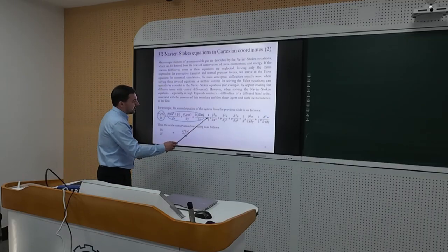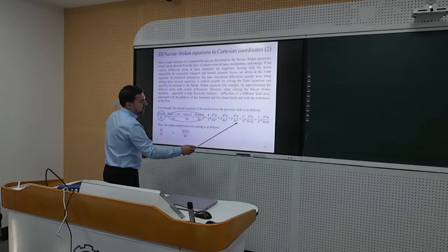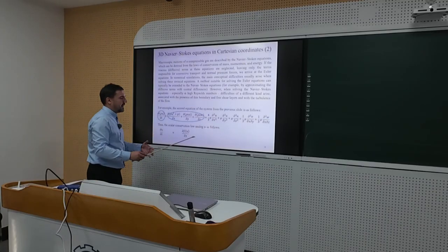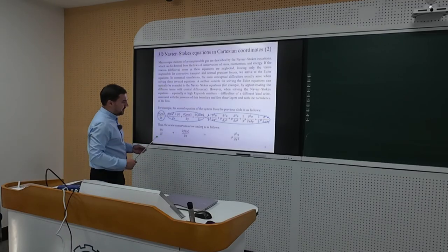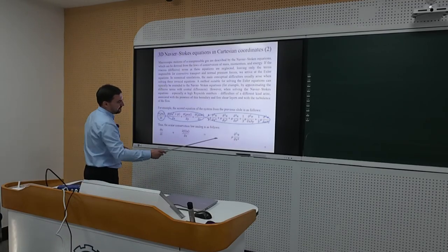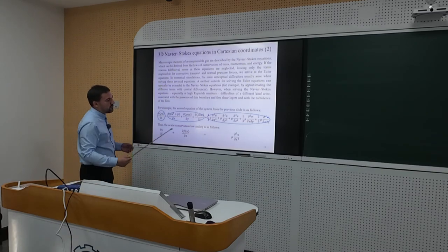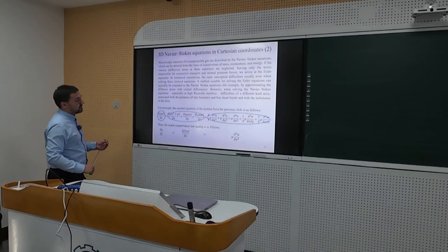And then here you can see all terms that are proportional to the second derivative of velocity, or mixed, but once again second derivative, proportional to some small parameter. Actually, here it's the viscosity coefficient. That is why we say, okay, let it be in our analog, we have this term proportional to the second derivative of our unknown function, mu d squared u over dx squared.